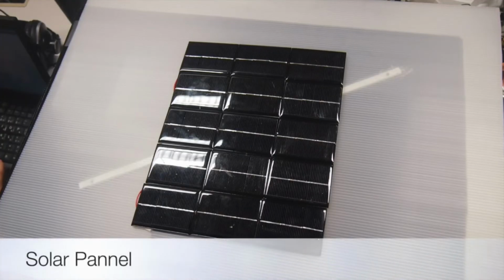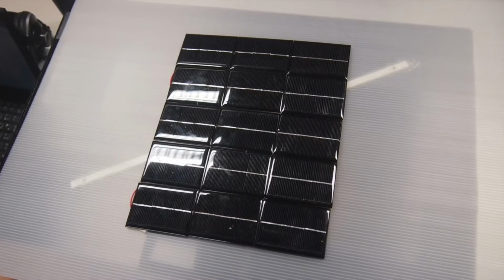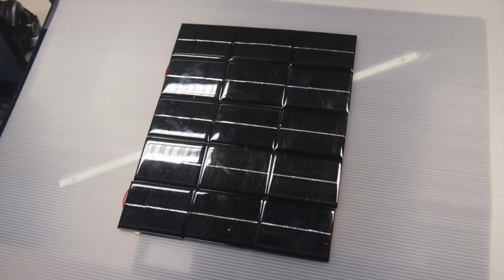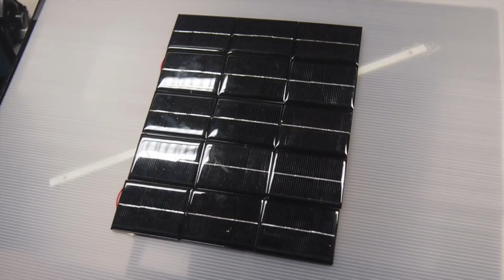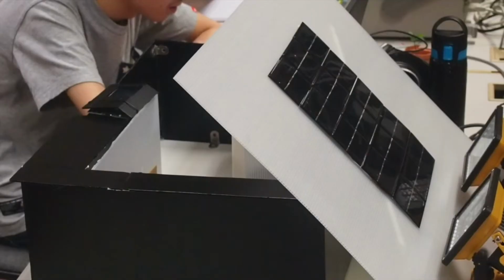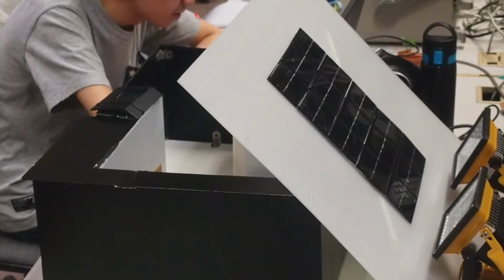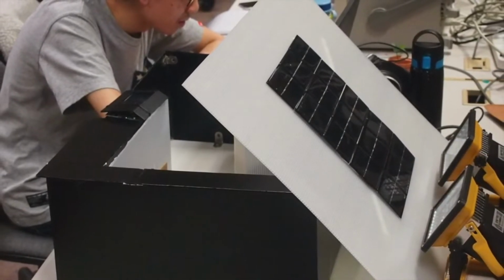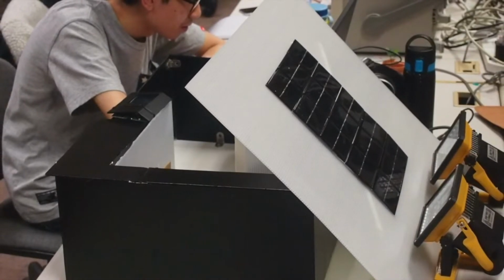Several solar panels are installed at the roof to collect solar power. We connected several of them in series and parallel to increase the total power aggregated by the solar panels. The energy will flow through a boost converter that increases the voltage to 5 volts, which is used to charge up a LiPo battery. A power management IC is installed to prevent overcharging and over-discharging of the LiPo. The LiPo is then used to power other systems in this project.